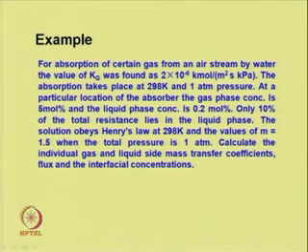At a particular location of the absorber, the gas phase concentration is 5 mole percent and the liquid phase concentration is 0.2 mole percent. Only 10% of the total resistance lies in the liquid phase. The solution obeys Henry's law at 298 Kelvin and the value of m is equal to 1.5 when the total pressure is 1 atmosphere. Calculate the individual gas and liquid side mass transfer coefficients, flux and the interfacial concentrations.